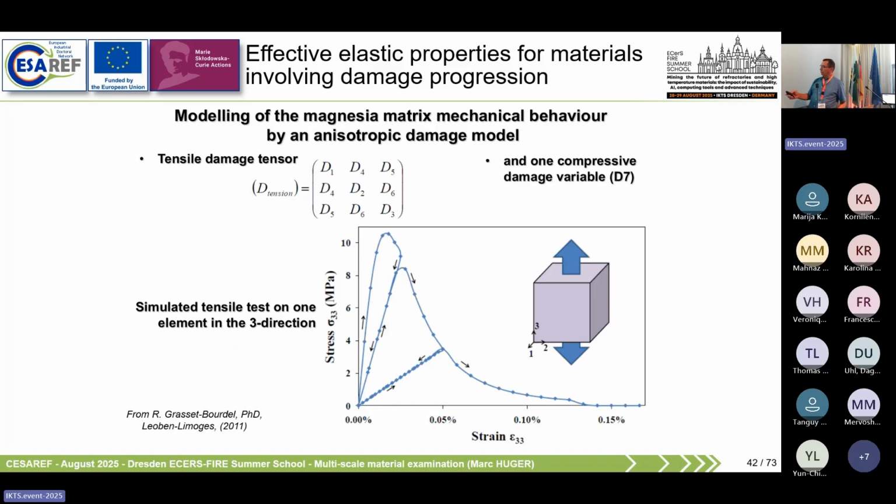And if you implement that in mechanics, you can implement an isotropic damage parameter, but if you consider that the cracks could be oriented, you have to take care about the orientation of those cracks depending on the loading. Then, instead of having an isotropic parameter, you need to introduce a tensorial parameter to take into account the orientation of the crack depending on the load that you have applied in a given direction. So you can see here that, if you play the game here, there is no evolution of damage. If you go to this point, you have an increase in the damage.